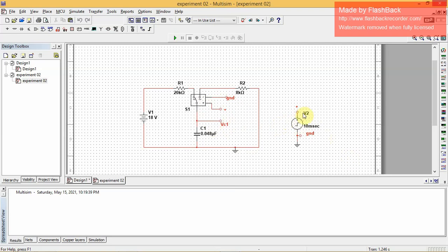How you use them is that the label on this on-page connector has to match what you want to connect it to. So this is a plus, and that plus matches this one. So in essence, I've connected this component's terminal to there, and this one is labeled GND. So I've connected this GND to there, and that's all there is to it. It's exactly the same as taking this, putting it here, and connecting it with a bunch of wires. It just looks neater this way.